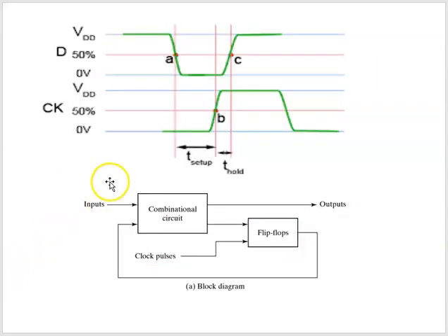If we zoom in and take another look, we're going to look further at these timing issues, but this is the essence of a flip-flop: a storage element that only transitions on the rising edge of a clock. If we consider this to be just one flip-flop, here's the input D, and here's the clock, CK. We're going to use a little triangle for the clock.